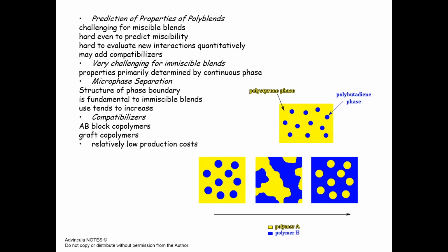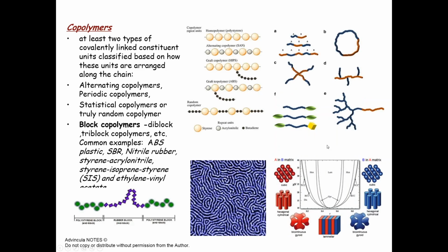Now, the control of this blending process is important because it can define, again, the thermomechanical properties. And between two polymers, you can have a range of compositions from 0 to 100%, and you can get a majority and minority phase. On the other hand, without blending, one can observe changes in properties by actually copolymerizing, or using chemistry to link these units together.